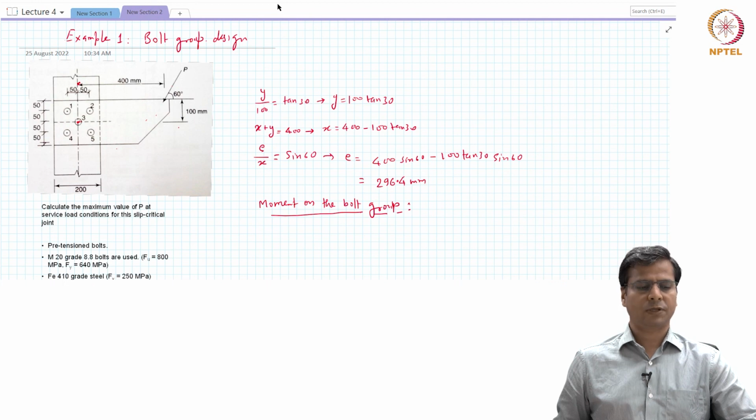However, if each bolt was not equally far from bolt 3, or if there was any other kind of asymmetry, then the new centroid location had to be calculated manually. It would not be obviously known that it is at the center. So the geometric centroid could be different from the centroid of the stiffness. In this particular case, both are the same, but if, let's say, one bolt was slightly stiffer or one bolt was slightly farther, then the centroid would shift its position.